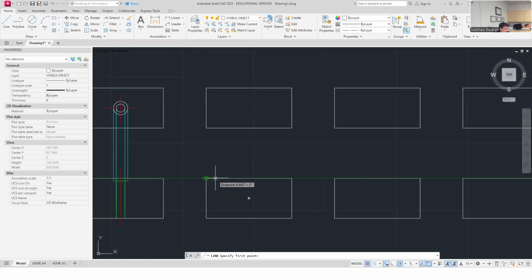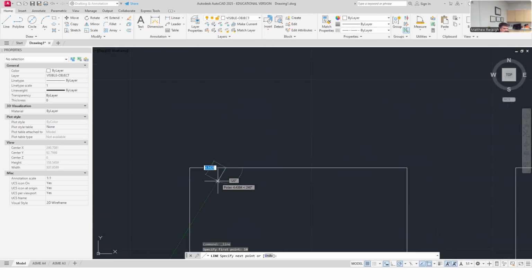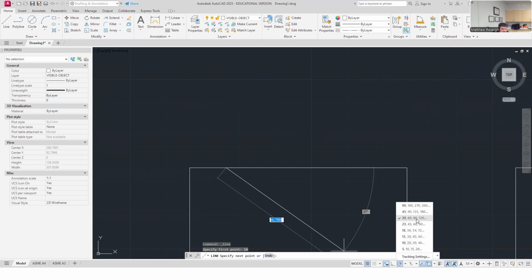Tells me that it comes over 10, so I'm just going to cursor over 10 millimeter. Then it goes down here to some angle, right? It's kind of the problem I have here. It's 60 degrees, it says. That's kind of handy. This one is one that I can pull or snap to pretty easily. I have my 30, 60, 90 polar snaps on.